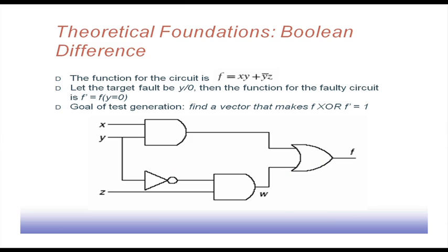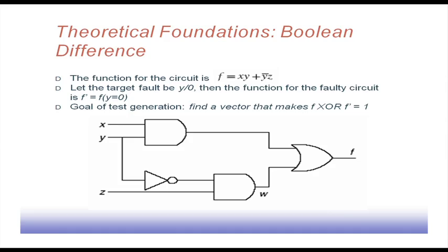So, next we will discuss this test pattern generation technique. But before going to the details of the test generation algorithm, we need to discuss some of the theoretical foundations of this testing process. They are based on one Boolean operation which is known as the Boolean difference operation. So, this circuit is realizing the function f equal to x y plus y bar z.